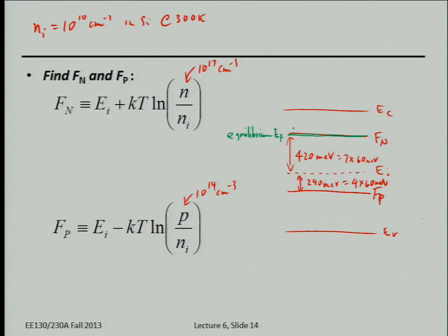Then let's say you shine light on this sample, so you enhance the hole concentration and the electron concentration, but it's a low-level injection, so you don't really change the concentration of electrons too much. That's why the Fermi level doesn't change for electrons. It's the quasi-Fermi level that changes for holes. So you need a separate Fermi level to describe the concentration of holes. So basically, you can view it as splitting the Fermi levels for electrons and holes when it's not in equilibrium.